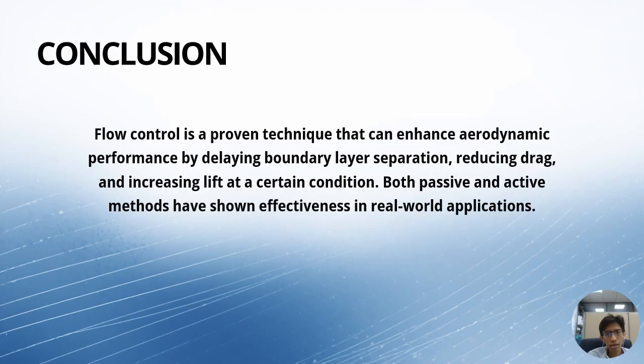In conclusion, flow control is a proven technique that can enhance aerodynamic performance. By delaying the boundary layer flow separation, it reduces drag and also increases lift at a certain condition, and both passive and active methods have shown effectiveness in real-world applications.